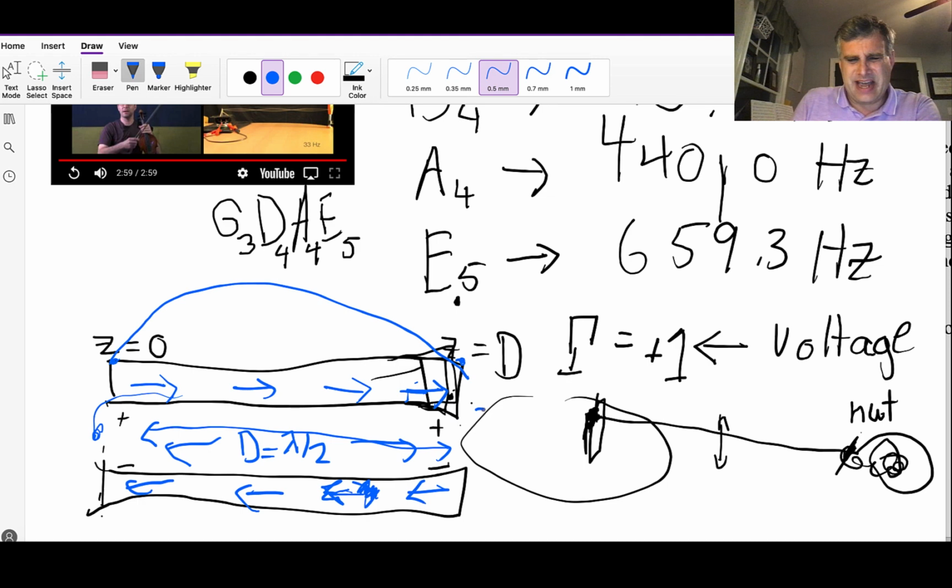There's a -1 reflection coefficient for the current waveform, so that means I've changed 180 degrees by traveling down the end of the line. The phase change at the end is another 180 degrees. I now travel the other direction. I have to travel another 180 degrees.